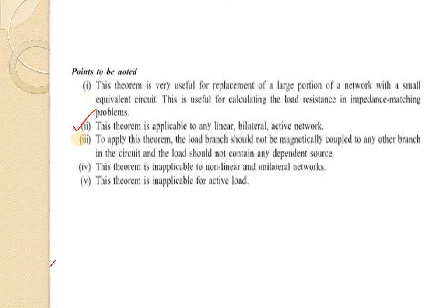This is a very important point. Third, to apply this theorem, the load branch should not be magnetically coupled to any other branch in the circuit, and the load should not contain any dependent source. Next, this theorem is inapplicable to nonlinear and unilateral networks. This theorem is inapplicable for active loads.